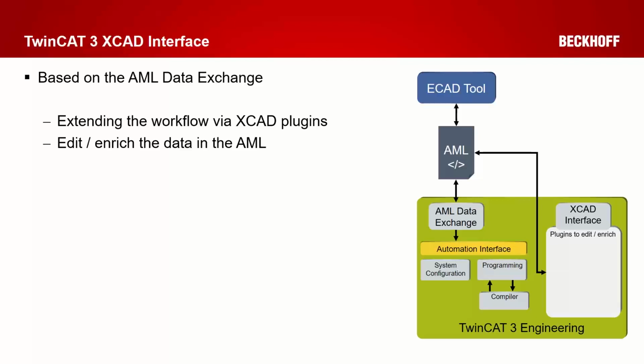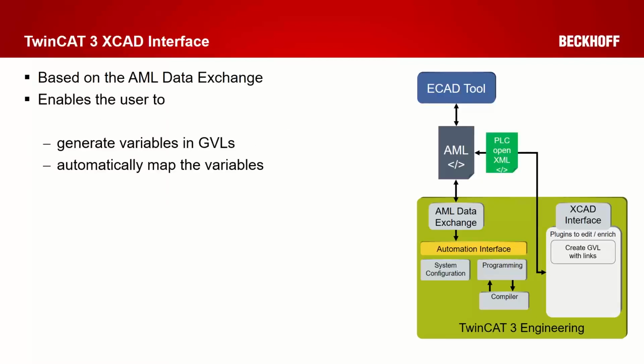So for example, we have added a specific plugin as a standard plugin, which is called Create GVL with Links plugin. As the name says, this plugin automatically creates a PLC project, a global variable list, and it automatically adds the variable to the global variable list and also automatically maps those variables to the I/O already.